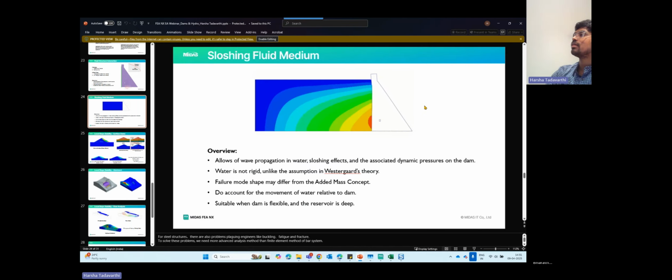So create a load set. So this is the load set. Let's say I'm going to consider load combination 2, LC2, let's say. I will select self weight, and let's say it is 1.2. And I will select hydrostatic pressure. Let's say it is 1. I will select tailwater pressure, maybe 1, but maybe let's say the uplift pressure, maybe around 1.2 again. And then I will press OK.